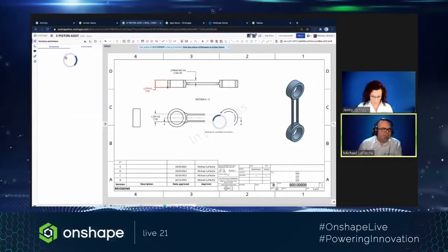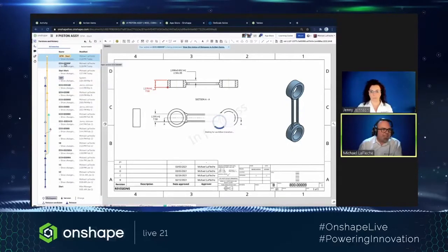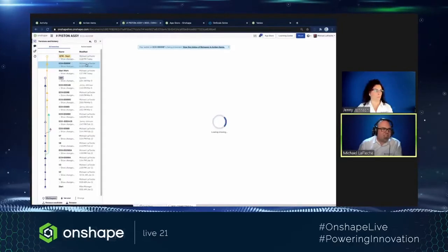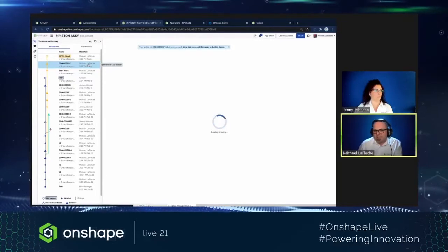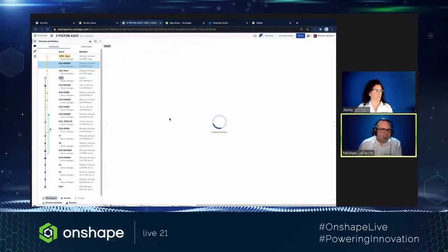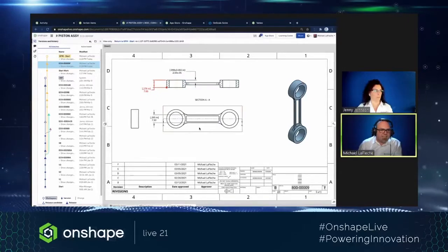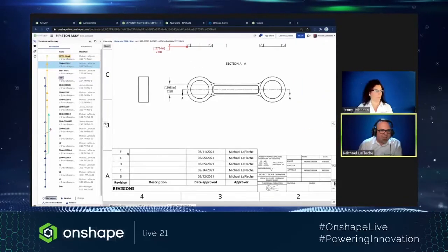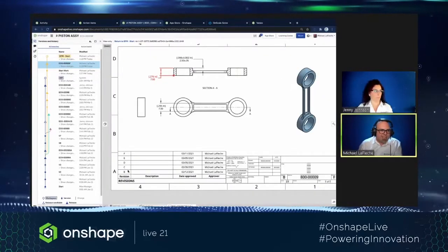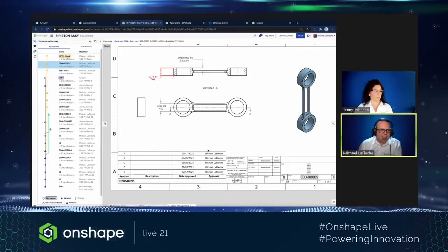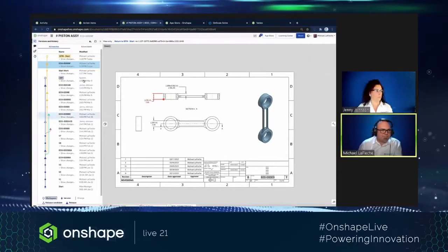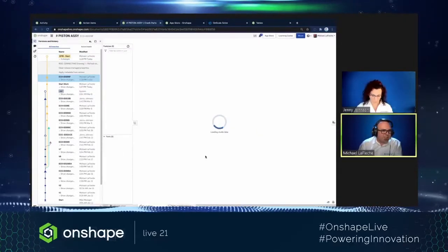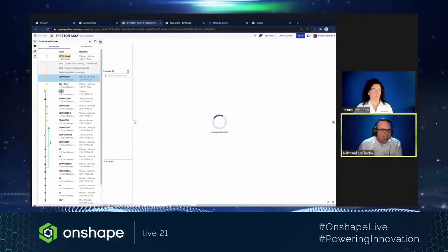If I look at my timeline view instead of my comment view, you'll see I have ECO 9F being generated right here. If I click into it, it will actually show me that released drawing right there. And you'll see on the drawing that the approval has been done, approved 311 right there. And there's Rev F. I have it set to cut off and only show me a certain amount of revisions here. So just like that, we have our release.